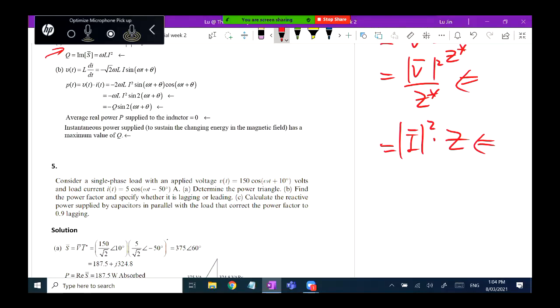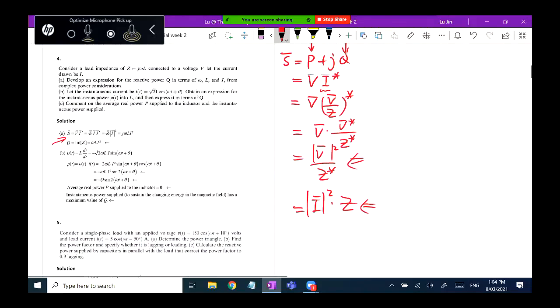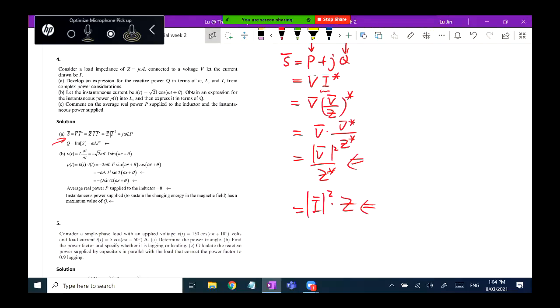Okay, so for this part, what we need to remember, I believe these formulas will not be given in the formula sheet, okay? So for calculating the complex power, this is important. VI conjugate, but you need to know V and I, this voltage and current must be vectors, okay? Or this one, be careful, the V is a magnitude of the AC voltage. It doesn't have an angle at all, and then squared divided by Z conjugate. Finally, current, same thing.